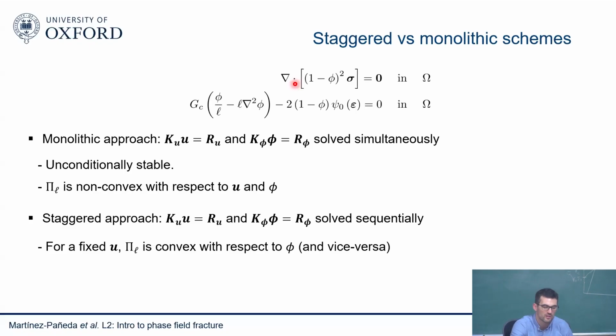If you do single pass, you could lose the unconditional stability. Single pass can be a bit more robust, you'll get convergence more easily. So if you deal with a very complicated, nasty problem where you're not getting convergence, you can use single pass, and I don't think I've ever seen any problem where you don't get convergence with single pass, but anyway, we'll discuss that later. With single pass, you'll get convergence, but then you become kind of a forward Euler type of approach. Because you are freezing and jumping between increments, if your increment size is too big, you may be deviating from the solution. So it's kind of an explicit approach. You may have to use very tiny increments just to make sure that you're not deviating from it. You need to do a time sensitivity study, basically.